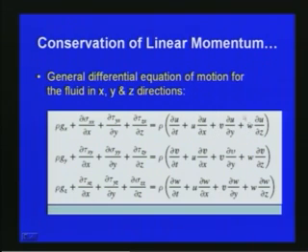So this gives the total acceleration in x direction. So mass into acceleration means rho into del u by del t plus u into del u by del x plus v into del u by del y plus w into del u by del z. This gives the general differential equation of motion in x direction.